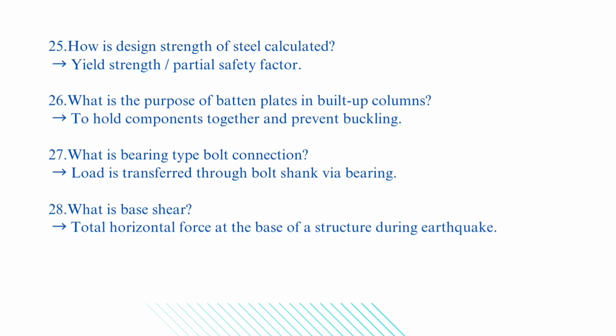The next is, what is a bearing type bolt connection? Load is transferred to the bolt shank via bearing is nothing but the bearing type of bolt connection. Then what is a base shear? Total horizontal force at the base of a structure during an earthquake is nothing but the base shear.